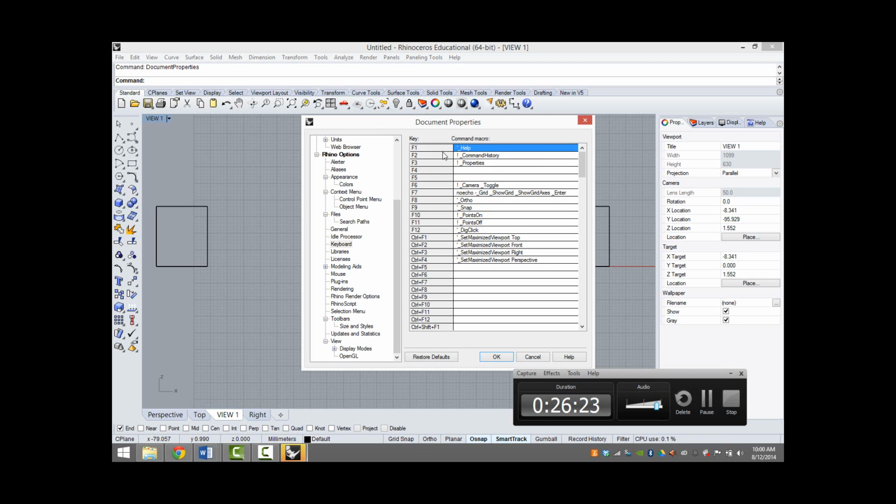Yeah, so any line that you draw will either be moving in the X or the Y direction, okay? Or the Z direction in Rhino. Many times people are wanting to kind of get into ortho mode quickly. I typically just click down here, and then here are all of your object snaps also. Or you can type O, I think is the hotkey, but I prefer O for offset.